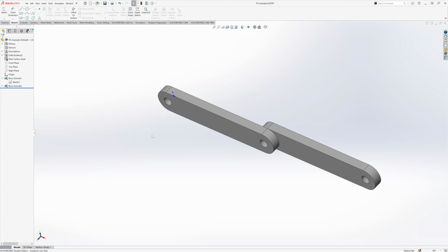So now this is a really quick example. Now let's go and jump into simulation. Last week I went over the spring connector, where if you don't want to actually have to model the spring and get the material properties right and everything, that's a very nice way to have simulation account for it without having to do a lot of modeling and a lot of contact work. So this is what I'm going to do. I'm going to do a similar thing, but I'm going to use what's called a pin connector to connect these two together.